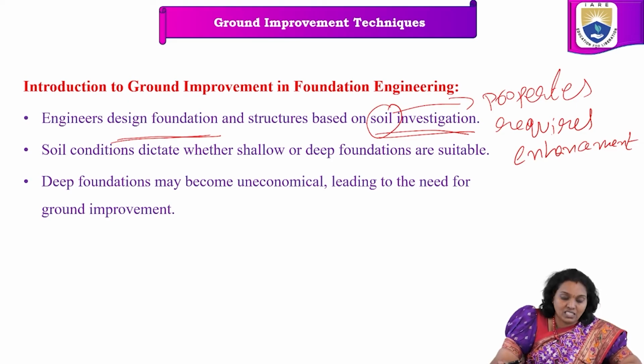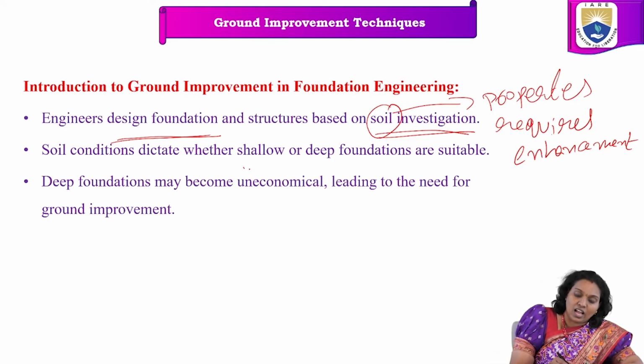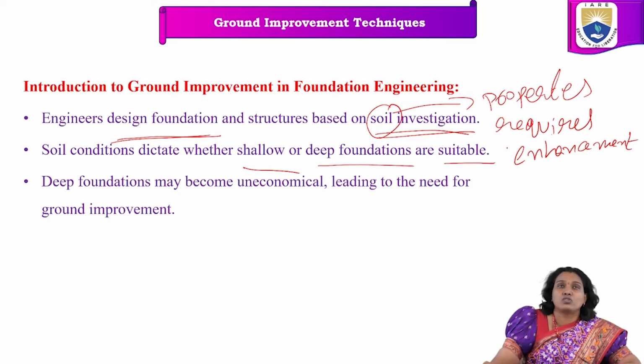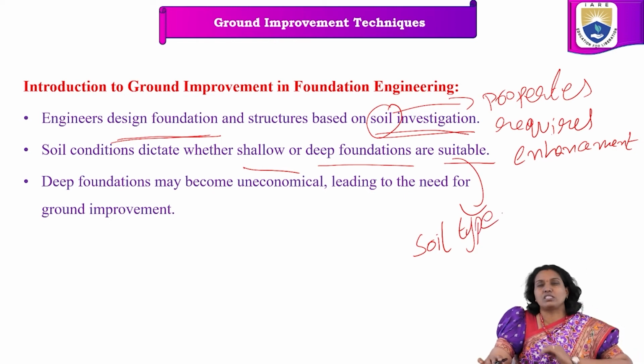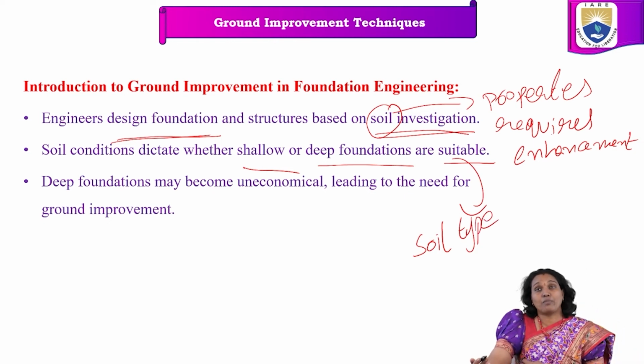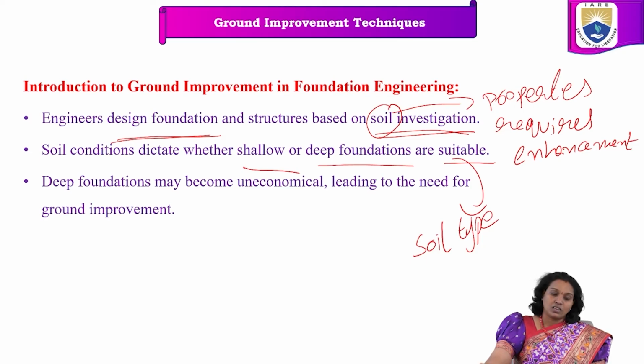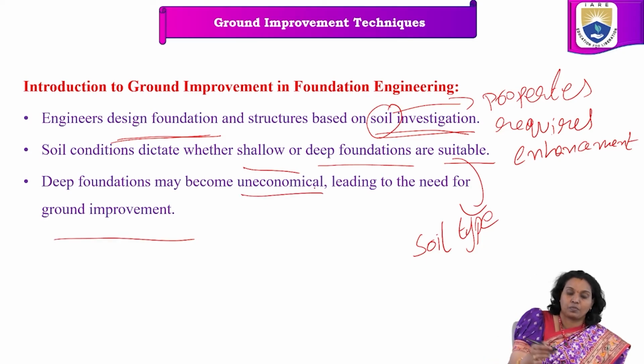Soil condition decides whether shallow or deep foundations are suitable. Which type of foundation is suitable or not depends upon the soil type. So deep foundation may become uneconomical, leading to the need for ground improvement.